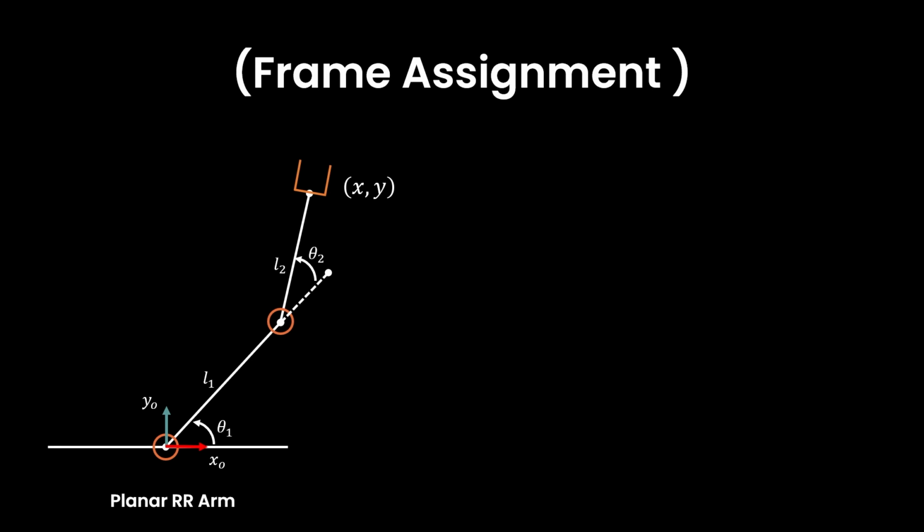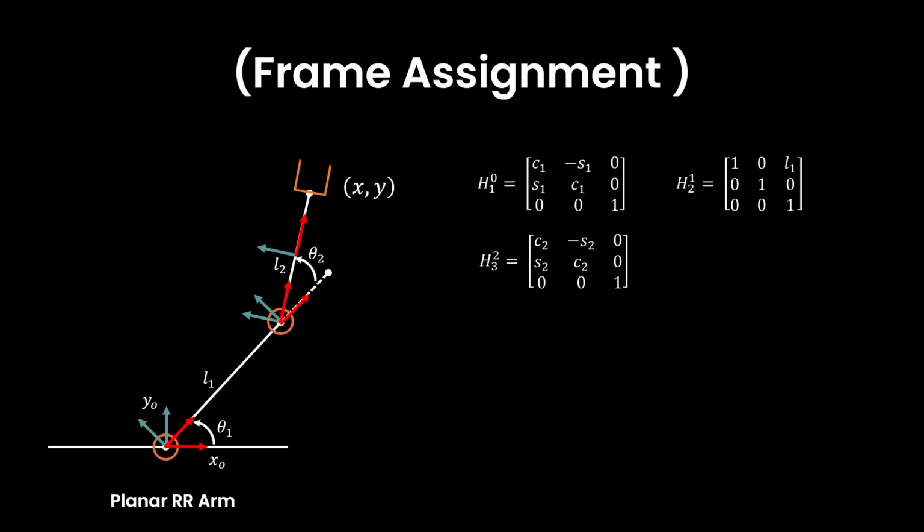Now let's find this end effector position using the information we just learned. With the homogeneous transforms of frames, the forward kinematics can be constructed by composing the rigid motion due to the individual joints. So we have 4 frames that represent the motion of the robot relative to the base. These 4 frames are the rotation due to joint 1, the translation of rigid link 1, the rotation of joint 2, and the translation of link 2.